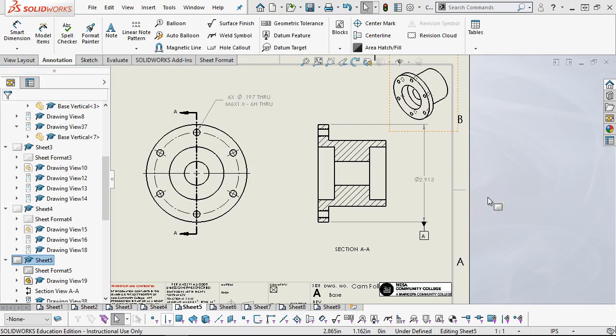All right, I'm gonna have to kind of think about how I want to do the positional. If that becomes the datum, then we could make sure that that was positional in the same size. This is going to be a press fit, though. If we just used a standard dowel pin, we looked at the other shaft here, and so that one was for the 17 millimeter. Let's go back to, all right, so minus 3/10 to 0, and so if we used even a standard dowel pin, we probably need to be a little bit even undersized of the 250, otherwise we're going to be using the green Loctite to make sure it stays in.